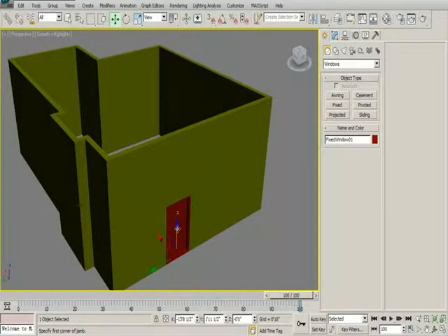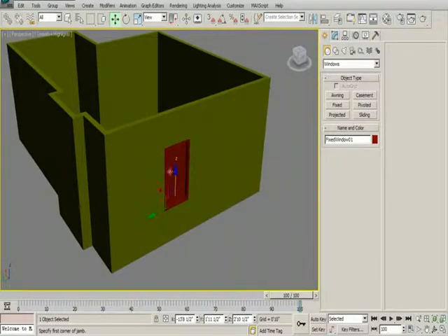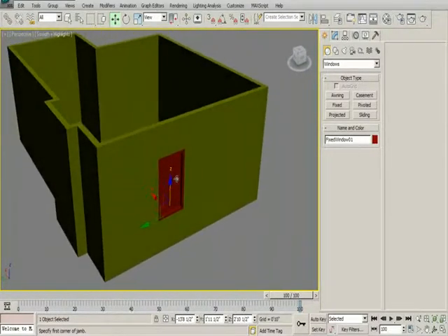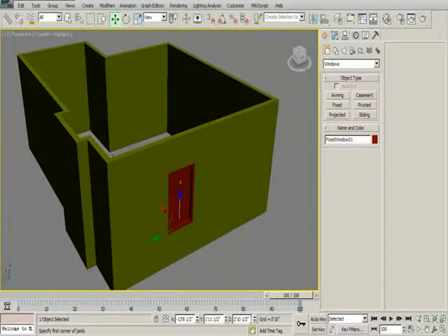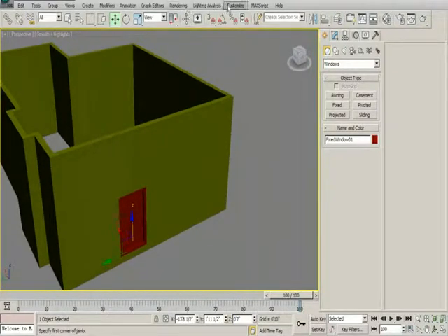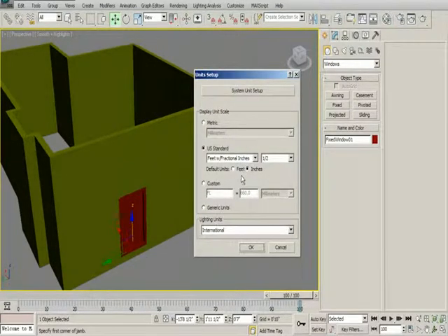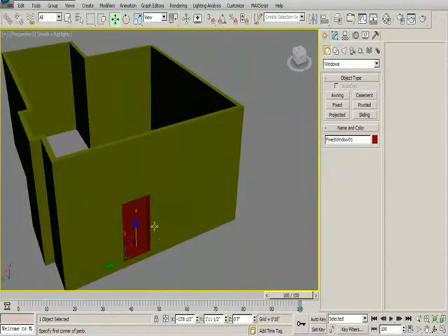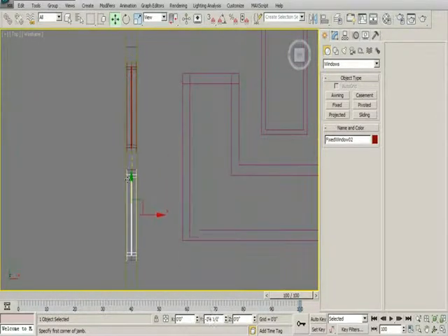If you move it in the Z axis, it automatically makes a place for itself, you can say. See here. So now I want to raise this up around 7 inches. Just type 7, it will take inches automatically, because of the unit setup option here, the default units. If you are working with feet, then the numeric you type will be taken in feet. If you are working with inches, then it will take inches. Okay, so let's make an instance of this window for our second window.